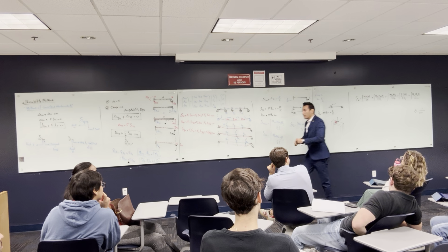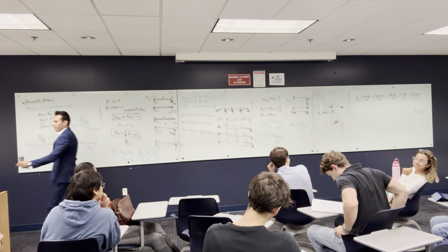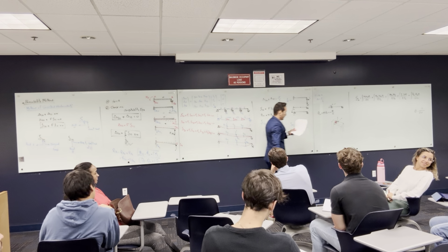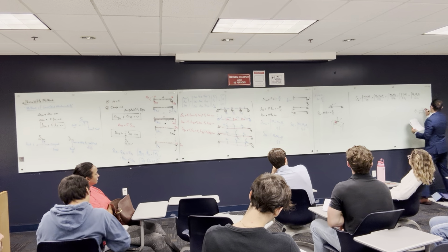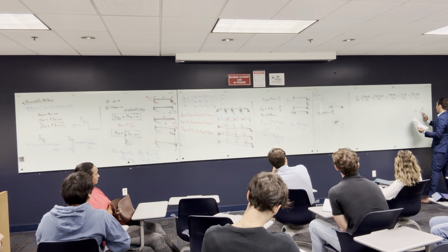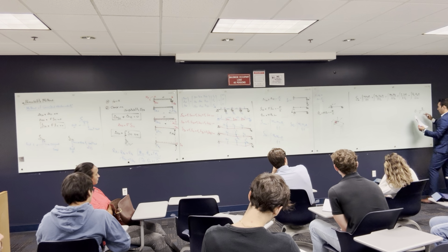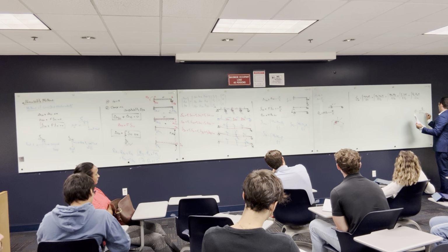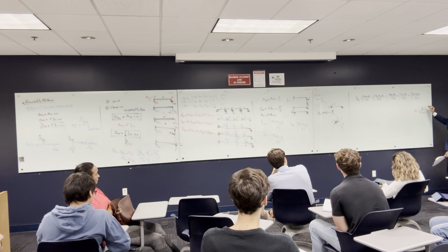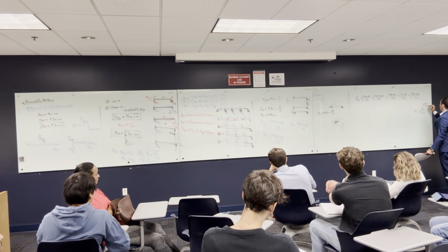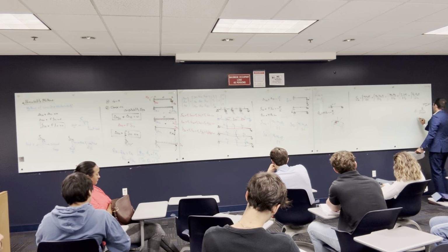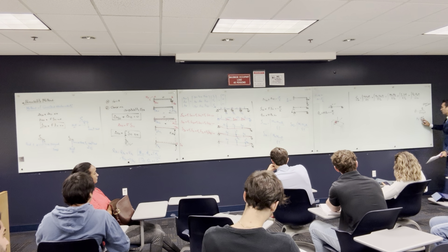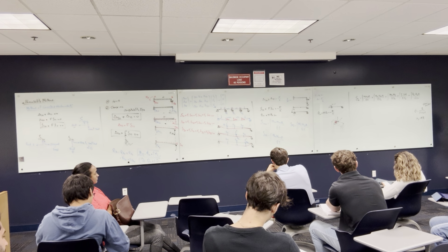Let me put the actual equation. Here is E, the Young's modulus, and here you definitely studied the shear modulus. I'm sure that you got it somehow in solid mechanics, mechanics of materials, plus the Poisson ratio. That is called the shear modulus. And AR is the reduced area, which is an alpha multiplied by the cross-sectional area, depends on the cross-sectional shape.